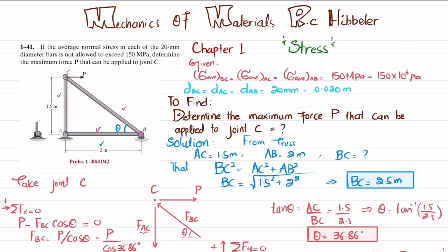Okay, so here at point B you can see that you have a reaction force that is due to this roller support at point B. This is By. Due to this member BC, there is a force which is in this direction FBC, and this makes angle theta with horizontal, and there is a load due to this member FAB. So the load will be like this one.